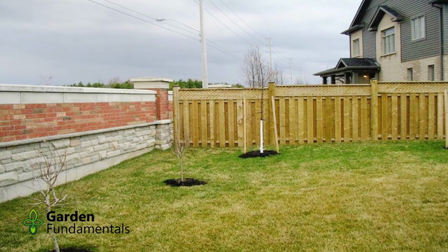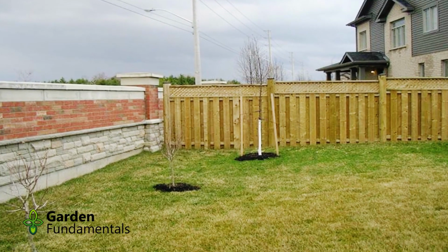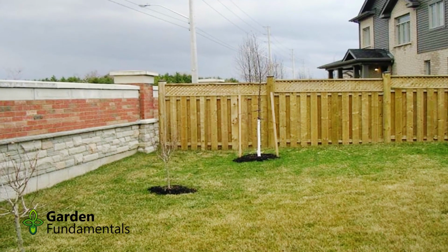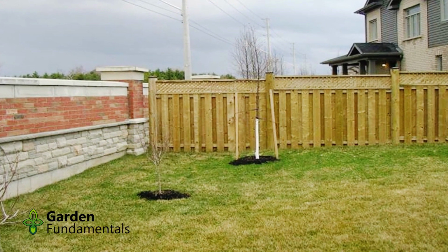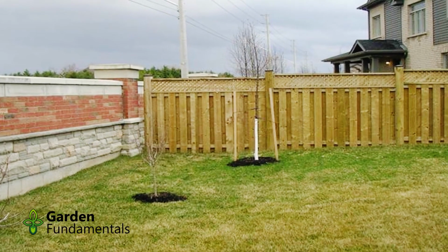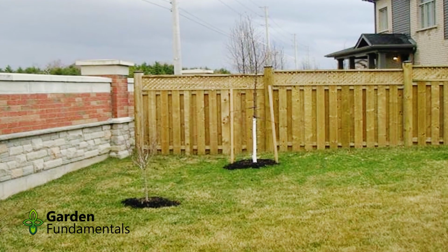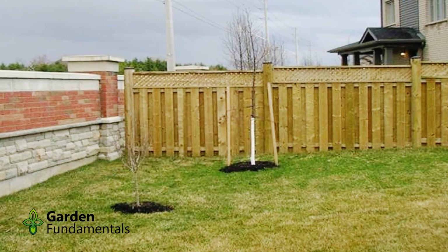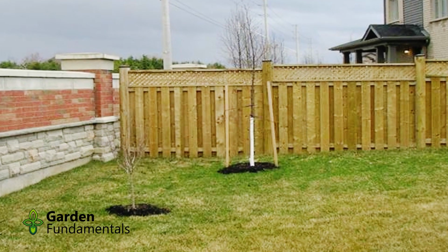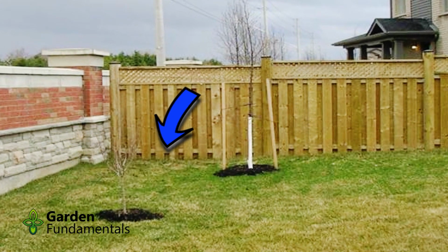There's another way that you can measure slope if you have a fence going across the property. So this is the view, the back corner of the property. If you have a look at the top of the fence going from right to left, you'll see that it jogs down a bit. And then you go across and it jogs down a bit. The reason for that is the fact that the ground slopes here. And in fact, towards the left corner, there's a bit of a swale. There's a low spot there.